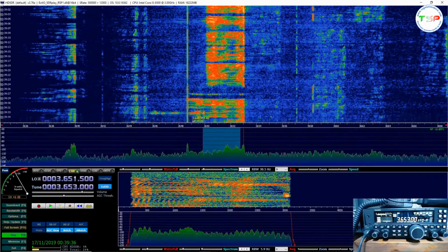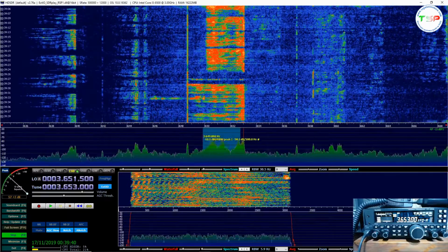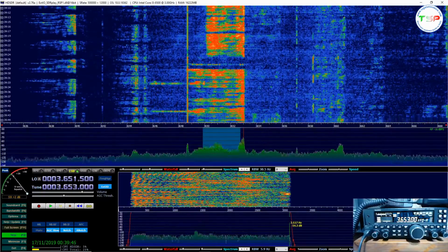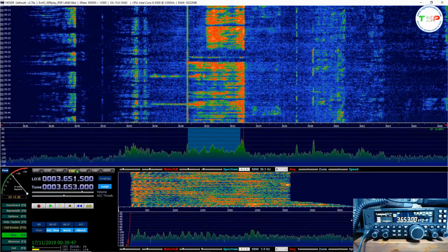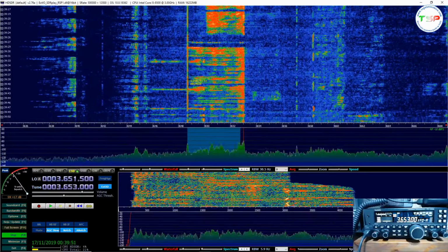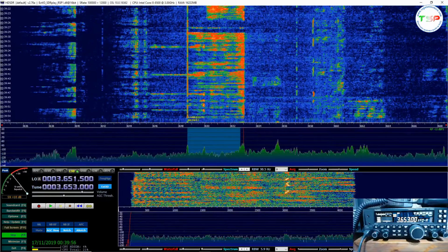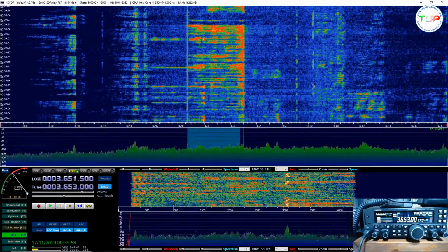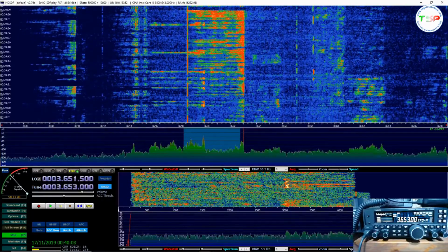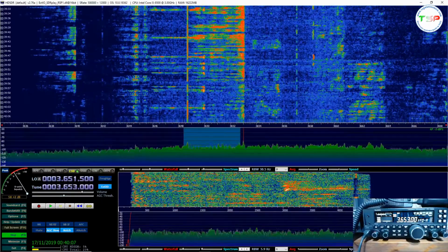And here you see also the bandwidth of the modulation. Okay, but I'm only listening on this part of the spectrum, so I can even make a wider filter in order to have a better reception. But when I arrive here, there's like a constant signal, so it can be a problem, you see. But now the auto notch started to work, you see. I removed the auto notch.